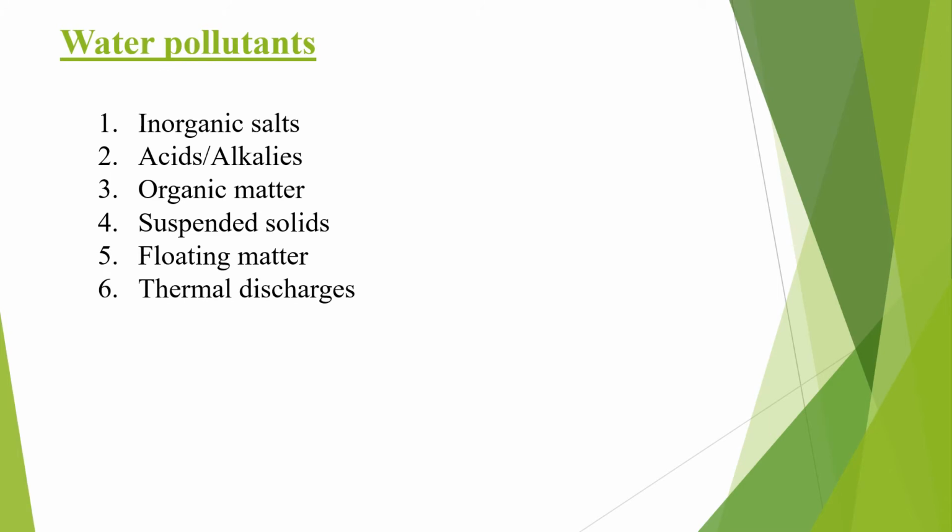Next water pollutant, thermal discharges. Increase in the normal temperatures of natural waters is caused by nuclear power plant or boiler or industrial discharges. Since warm water is lighter than cold, stratification occurs in the water body and this causes most of the aquatic life to retreat to the stream bottom. Also, bacterial action increases, which in turn results in accelerated depletion of the stream's dissolved oxygen content.